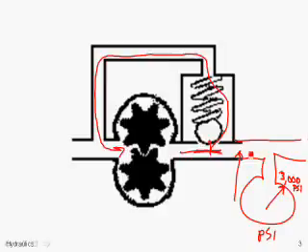So if we turn something on and fluid goes into the system, then the pressure in here would go down. This ball would close off, and now all of the fluid coming from the pump would go to the system, and the pressure would come back up to 3,000.